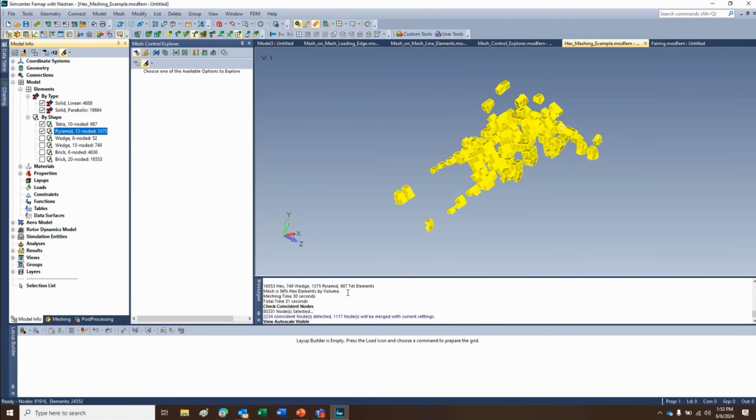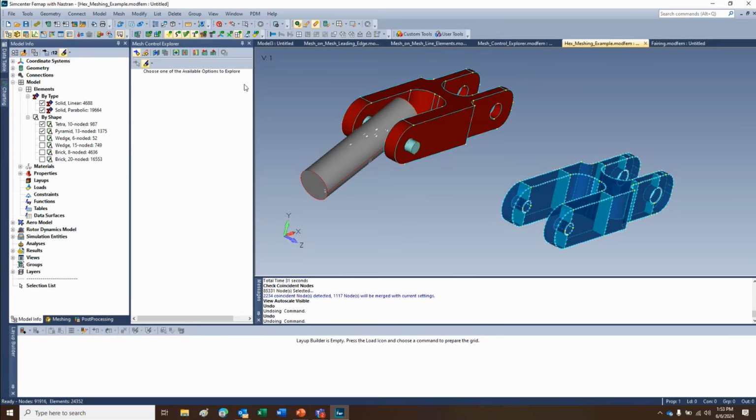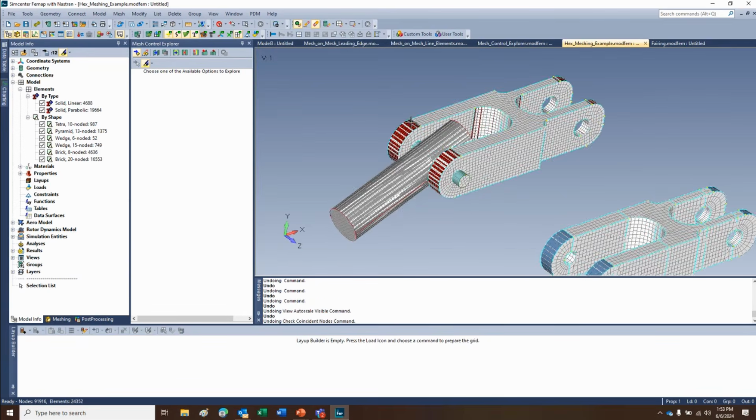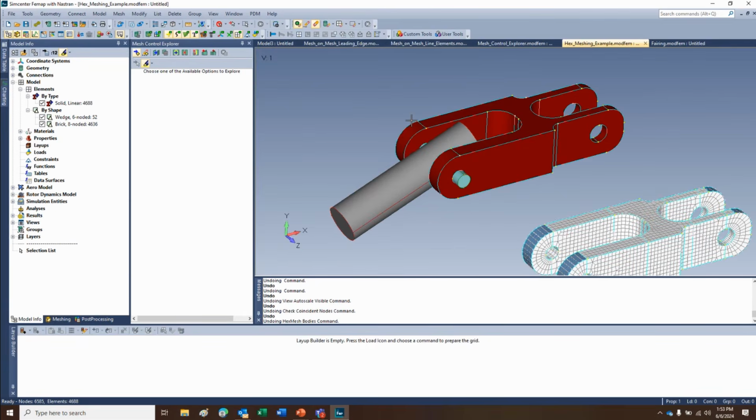Are there ways to put in a mesh approach for your lug? Well, you can do smaller elements. If you tighten it up, you can get better round holes and stuff. You can juice it down in that area and you'll get a better mesh, and that automatic connection will make sure it's connected. So you can do somewhat, but you can't be guaranteed things because it's basically designed to be automatic.